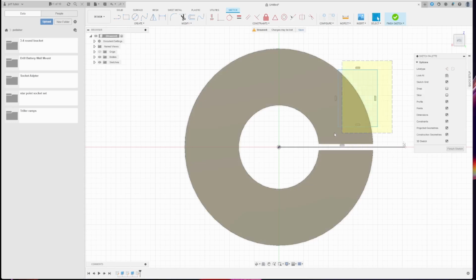And sadly, they're not called construction lines inside of Fusion 360, but we can just use standard lines and go with that. Now we'll pull up our mirror tool after we selected our square, and we'll select our mirror line. And you can see it gives us a nice box, but I'm also seeing that I now have 8 selected instead of 4, so I'll hit the X and I'll reselect them, and we have 4. So now I can go ahead, hit OK, and now I'm going to get those 2 boxes. So when we actually take and slice this, it's going to take this material off top and bottom.